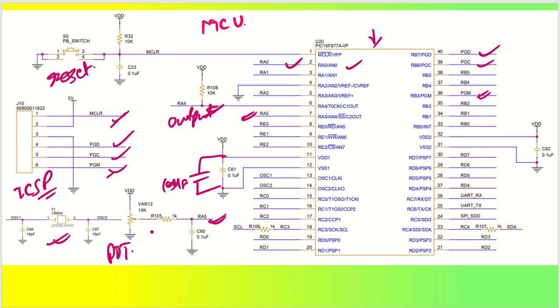The VDD, which is 5 volt, will be divided by this resistor division and then passed through this low pass filter, which is a 1 kilo ohm and 0.1 microfarad RC filter, and then goes to the analog pin, which checks the analog voltage at this pin. Other pins are the SCL pin, which is your I2C clock line, and then the I2C SDA line is here.